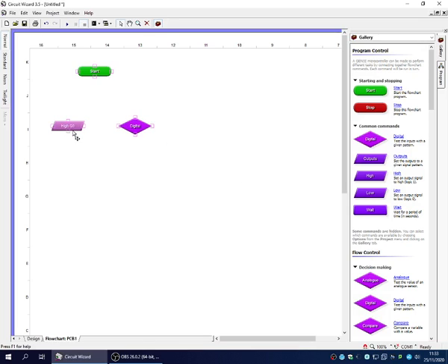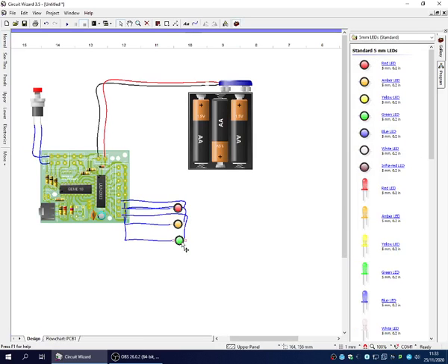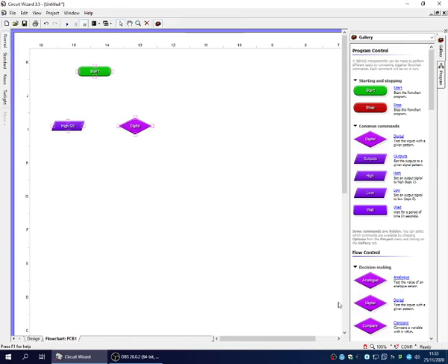It will just say which one is switched on. High on Q0, which means we'll get a green light. Now it's important to say when things are off as well, because had the last command been illuminating this red light, and we don't tell it to turn it off, it will stay on. I'll show you in a minute.